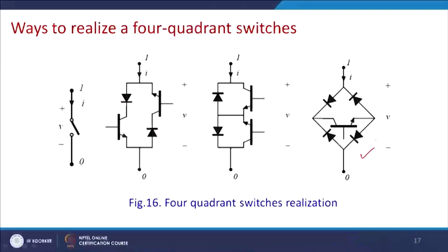So, for this reason there are a few realizations of this circuit. The voltage and current are required to flow between point 1 and 0. This can be realized by many switches. A normal mechanical switch is automatically of this configuration. Let us see how this can be realized by semiconductor switches. So, we shall take the rightmost circuit first. In this circuit, if V1 is greater than V0, then the path of the current will be through this.